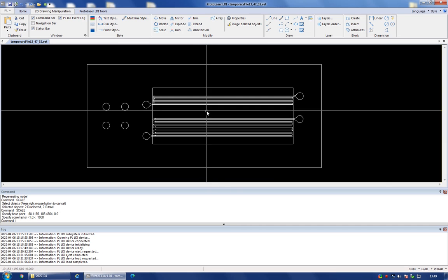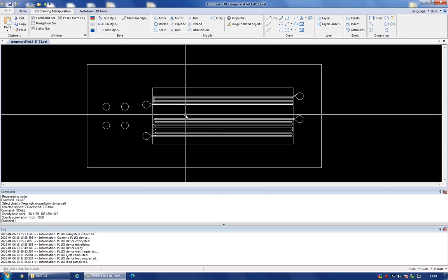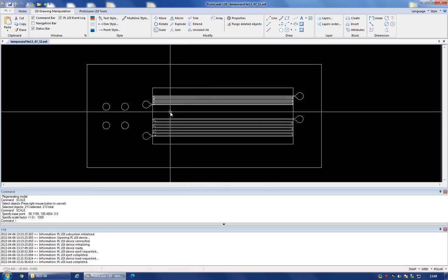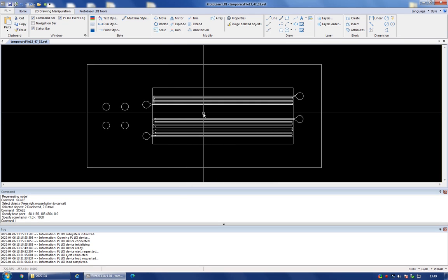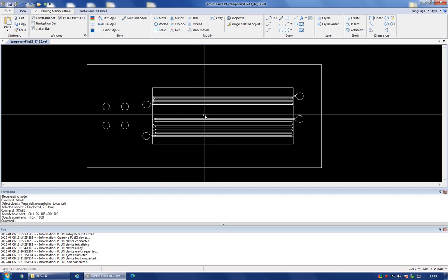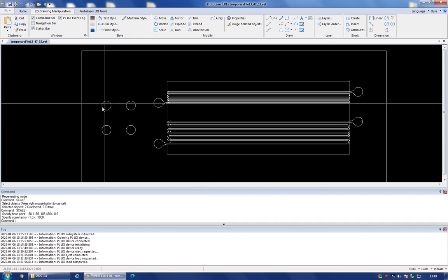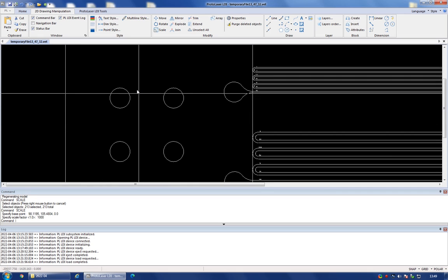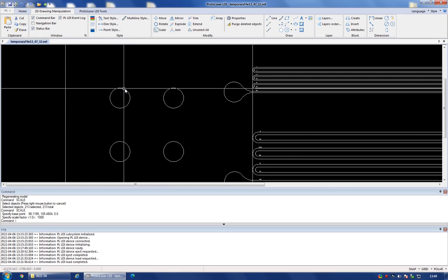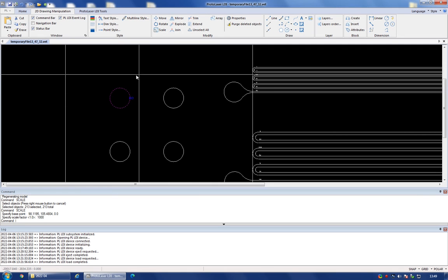So moving on to what we do next. The way that the software works is that you have to provide it some enclosed shape. So any enclosed shape, which is delimited by a single line, can be converted into an area that the laser writer will expose. So for example, these circles that I've put in here, which are some practice inlets for punching in the PDMS, I can select this, and you can see that this is one single enclosed shape.